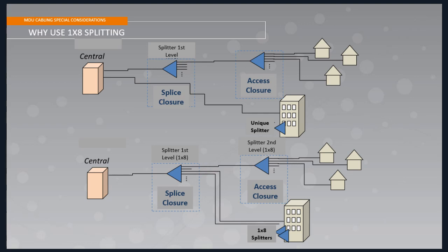So at the end, there is no differentiation of SFUs or MDUs. You just place as many splitters as you need in the basement of that building, making the design much easier. You treat each customer of that building as an SFU customer, but at the end you just aggregate the splitters in the same box in the basement of that building. It's bringing the design to the very same level, independent of whether the customer is SFU or MDU.